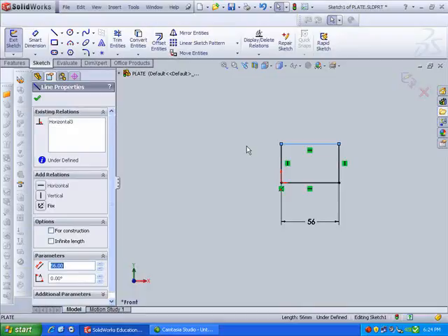There were two that were larger than the other. Consequently, the part didn't fit or didn't hold the drill. So make sure you deal with fully defined sketches. You want your sketch to be completely black.